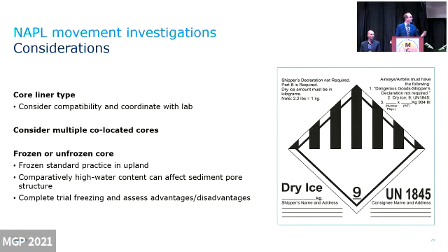You also might want to consider collecting multiple cores at a given location, as the standard recommends, because perhaps you might want to run a centrifuge test on one interval and then in the adjacent core, run a water drive test on that same NAPL observation. Maybe you'll want to get some hydraulic conductivity information of the overlying sediments to inform the pore entry evaluation that Mike had described, or just having a core on standby is always helpful, and it's easier to gather that while you're at that location in the field than remobilizing at a later date.